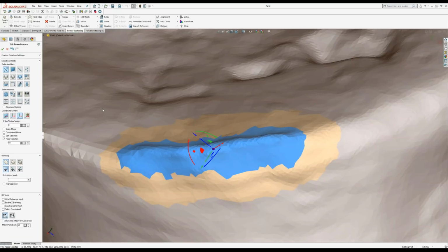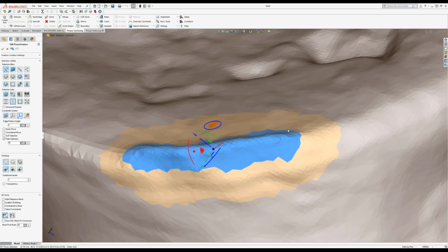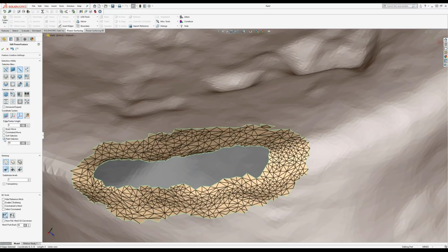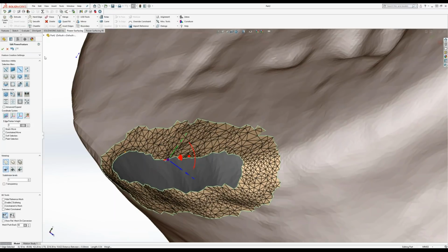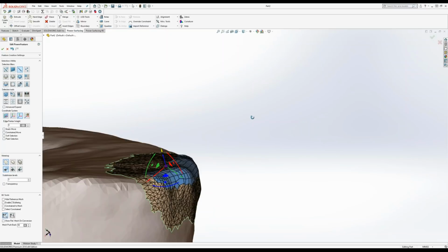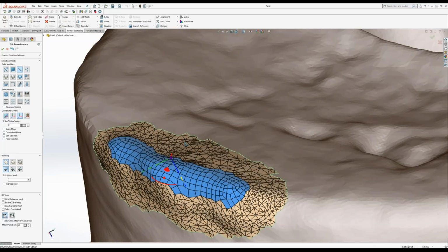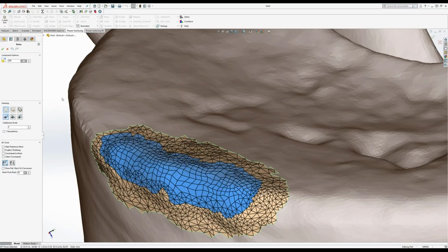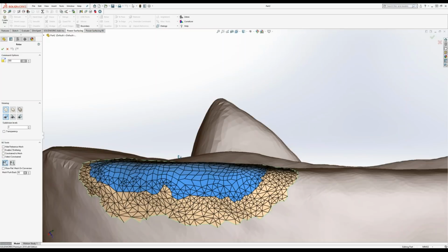That's another way. And a final way to do it is, let's shrink down our selection a little bit, to actually go in and delete these. So if I have some bad geometry there, that might be a better solution, for me to actually delete them. Turn off paint selection here. I'm going to grab an edge, and I'm going to use our quad fill command, which is a very powerful command, to fill that guy up again. And you can see it's done a fairly decent job there. And then once we've done that, maybe we want to expand the selection a little bit and then run the relax on it. So you can see you can replace areas of your mesh very quickly and very easily, get them much smoother, that sort of thing.